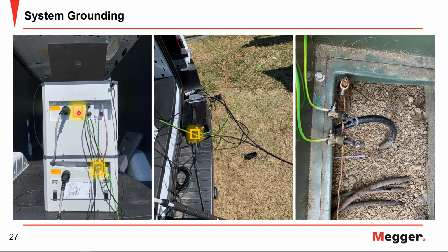You don't want any ground loops or loops that would create an antenna effect. The second ground is from this communications box here, and we can see those grounds coming out nice and straight, and then coming in to our grounding point within our junction box, right? So again, that's going to be the very first connection that we make.